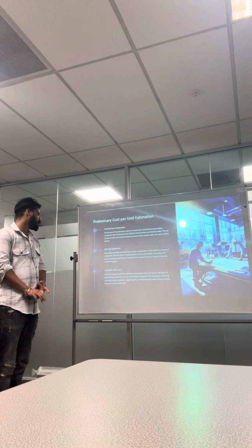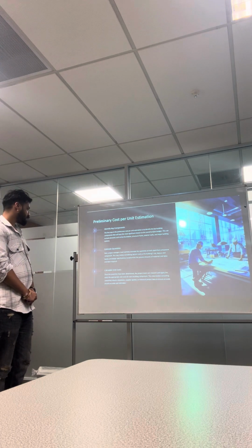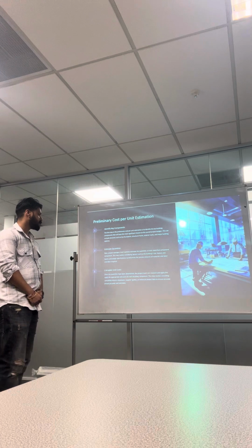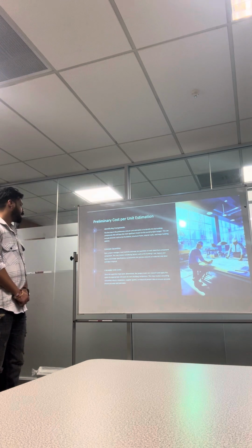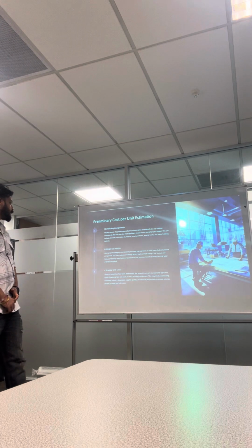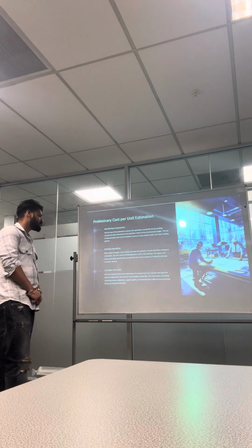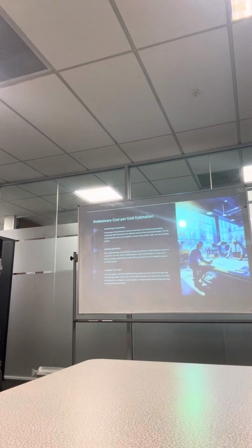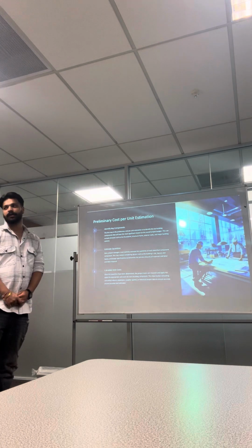Third is calculate unit cost. Once the quantities have been determined, the project team can research and apply the appropriate unit cost to each building component. This may involve consulting industry databases, supplier quotations, and histories of projects which we have done in the past.